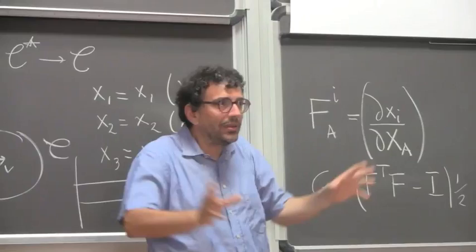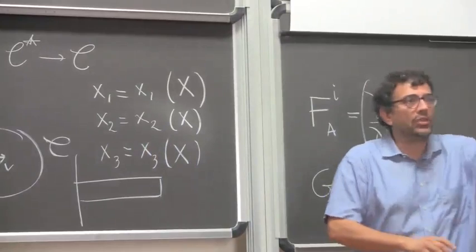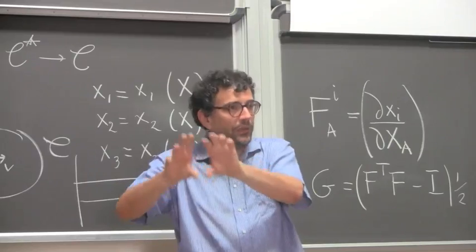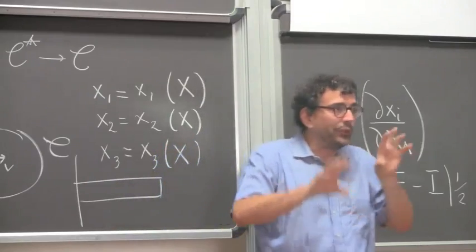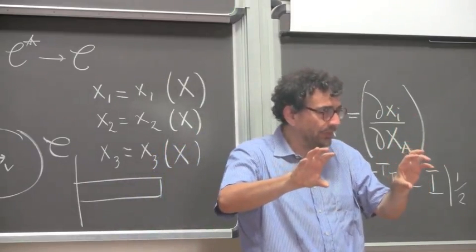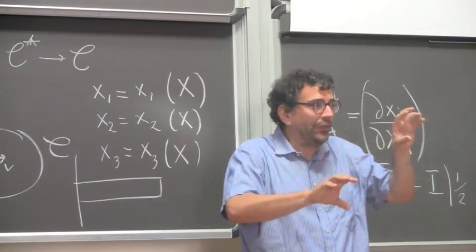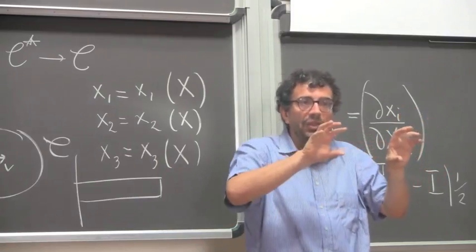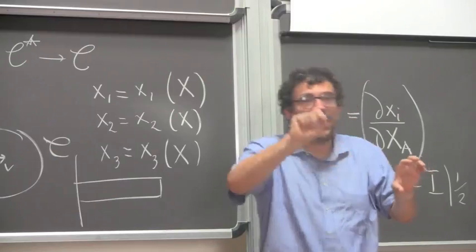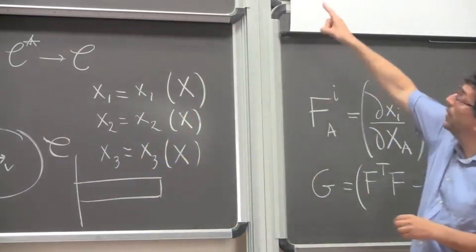I gave you the whole presentation, starting from the energy. I said I want the minimum of energy, and I calculate the first variation of the energy. This energy was made of two terms, deformation energy and external energy. We equated the first variation of external energy plus the first variation of internal energy, the deformation energy, to 0, and we wrote the equilibrium equation.